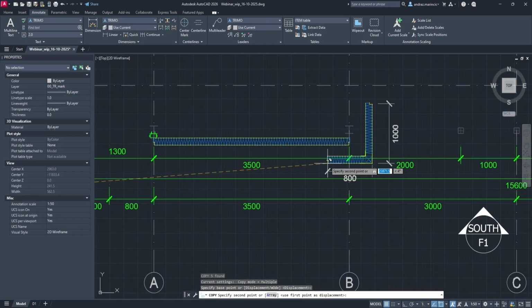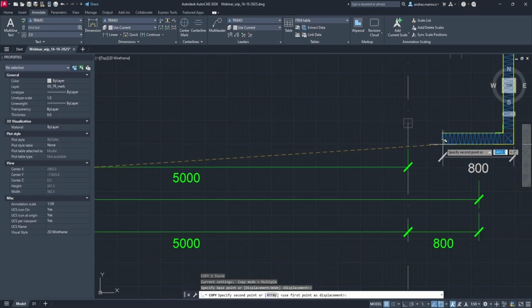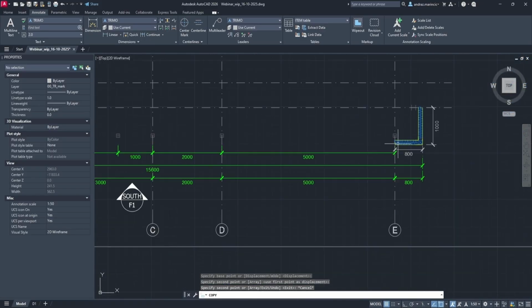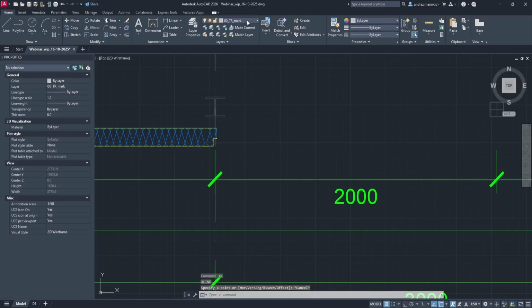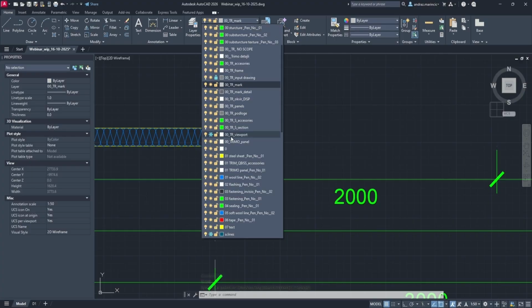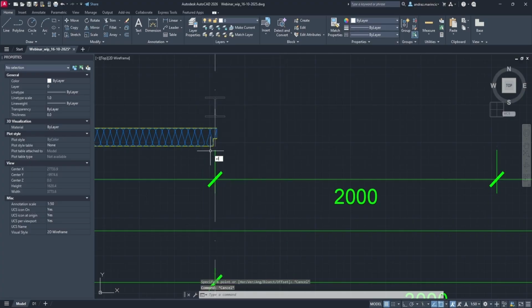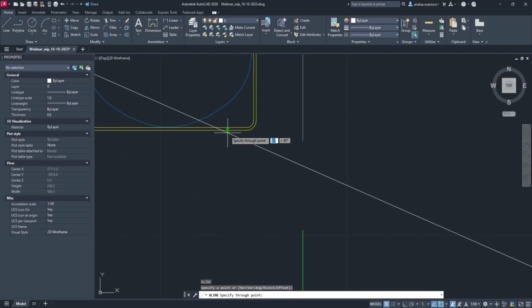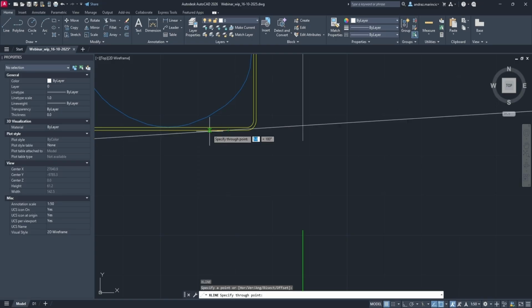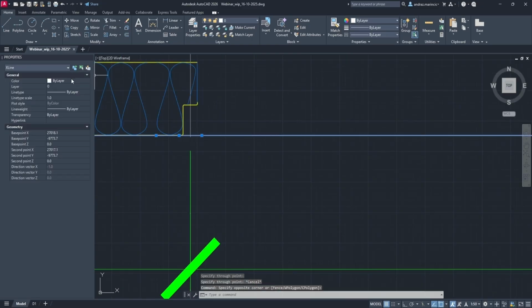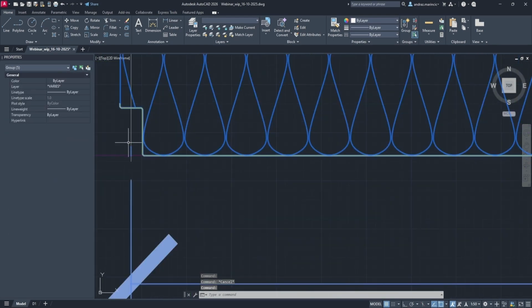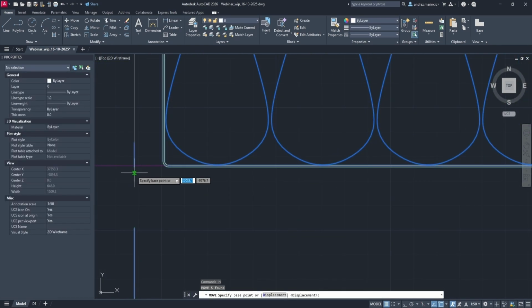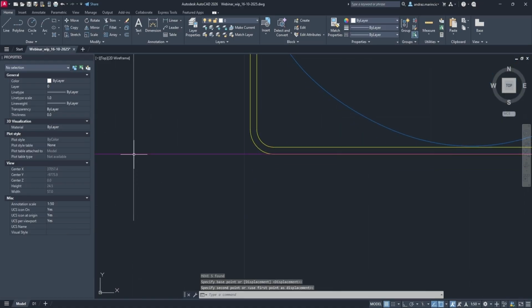Now I will simply copy that to that side of the building. I will just use some guidelines, some construction lines. A little bit my construction line, I will put it in magenta, so the facade can be aligned as it should be.